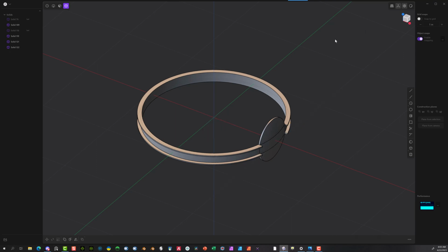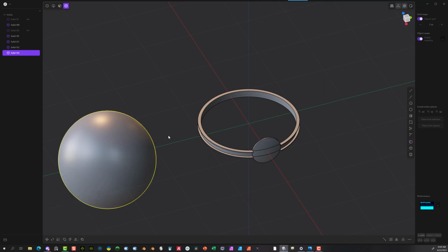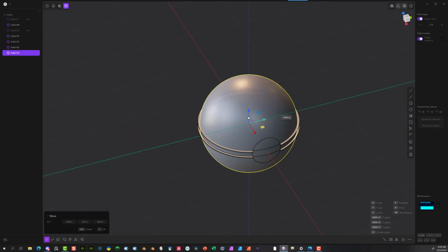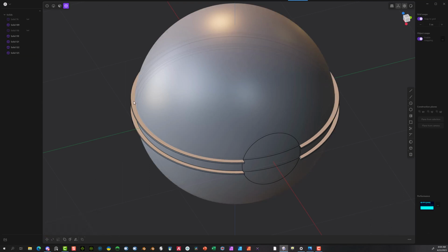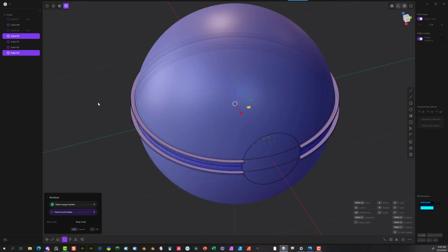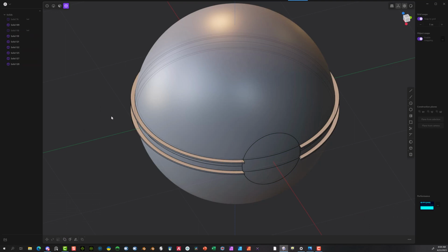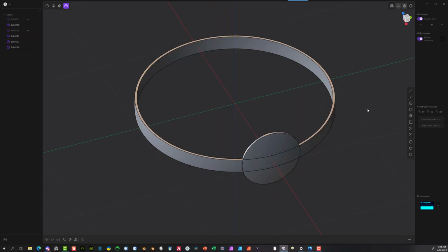There's two curves. Hit this. Bring it out. I'm going to do 0.96. Say OK. And now what we can do is select it, hit the G key, move it in place. And what I'm going to do here is cut this section out. So say OK. Select this first, then this. Hit the Q key, hit the Shift Q. Say OK. And then you can select these outer sections. Hit delete. And there you go.